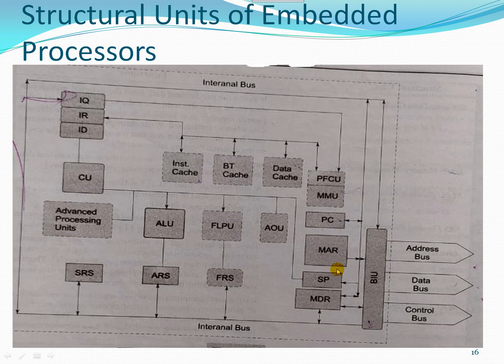So to fetch the instruction, we are given the address which is in the program counter. By using this address, we will be fetching the data at that address using the memory address and memory data registers.